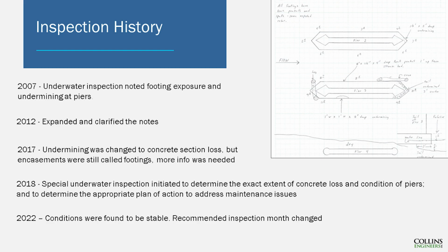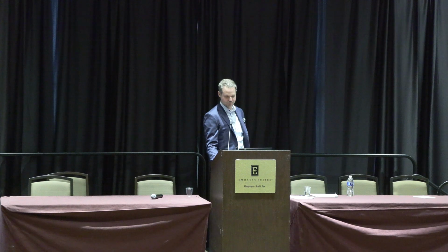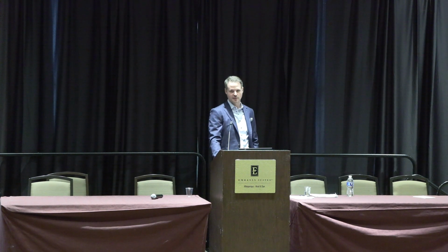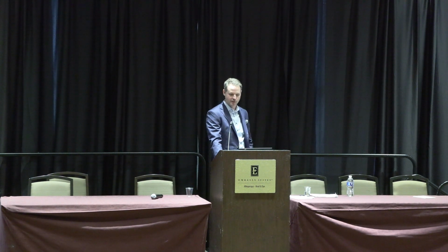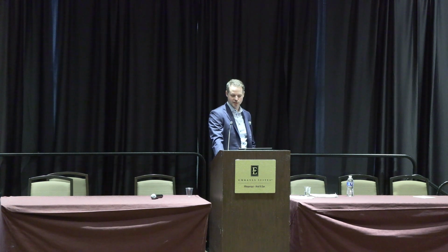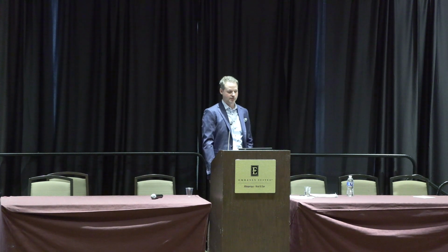The problem was that the defects on this bridge were being characterized as a scour of the footing issue, but no one was really sure how serious it was because it's hard to inspect. There wasn't a lot of information. Since there was confusion about how much of a threat the scour and/or section loss was to the bridge, we decided to do an in-depth inspection and to take a look into the history of the bridge to figure out what was going on.